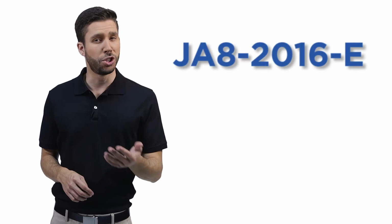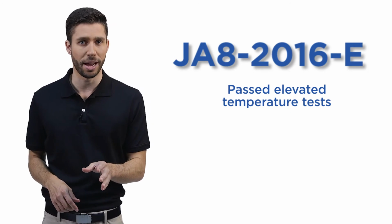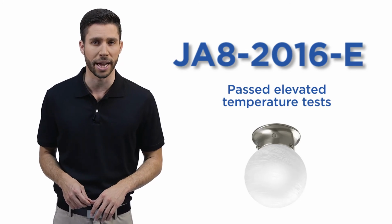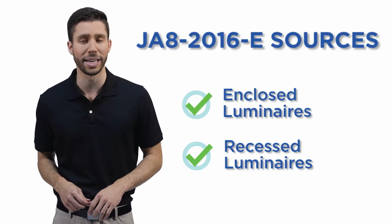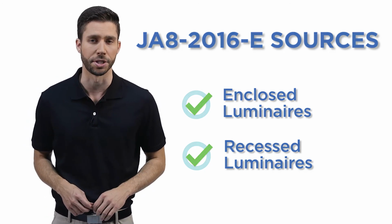Light sources marked with JA8-2016-E have passed the elevated temperature life test, indicating that they comply with JA8 criteria and may be installed in elevated temperature applications, such as in enclosed and recessed fixtures. Only JA8-2016-E light sources may be used in enclosed and recessed luminaires.